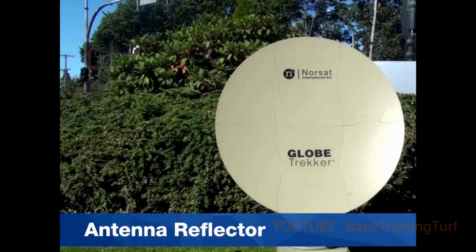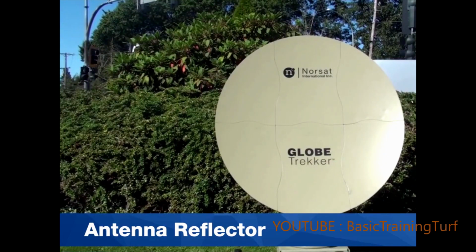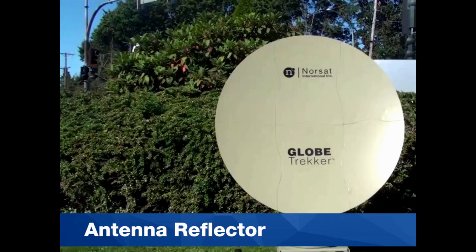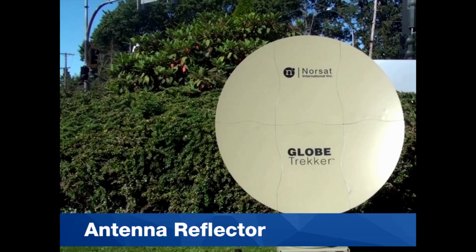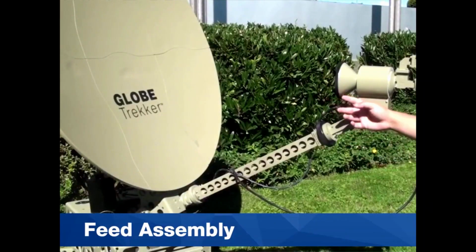The satellite terminal has an antenna reflector, also known as the dish, which is made from aluminum, fiberglass, carbon fiber, or steel. The purpose of the antenna is to capture a signal from the specific satellite and send it through the feed assembly. The larger antenna you have, the more signal is reflected into the feed. The feed horn at the front end of the waveguide channels the incoming and outgoing signals from the antenna.